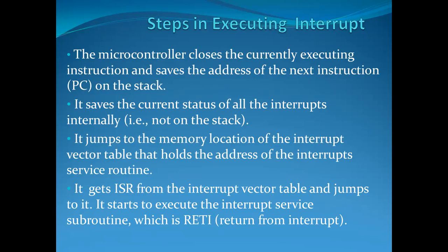It jumps to the memory location of the interrupt vector table that holds the address of the interrupt service routine, gets the ISR from the table and jumps to it. It starts executing the interrupt service routine, which ends with RETI, return from the interrupt.